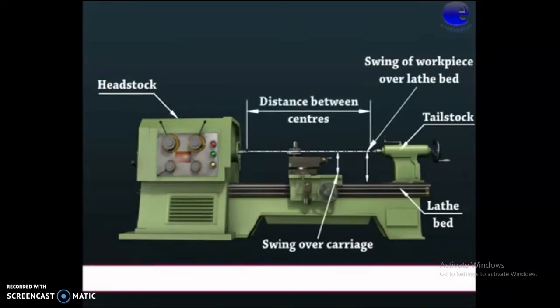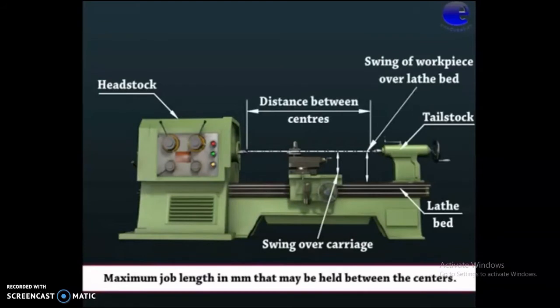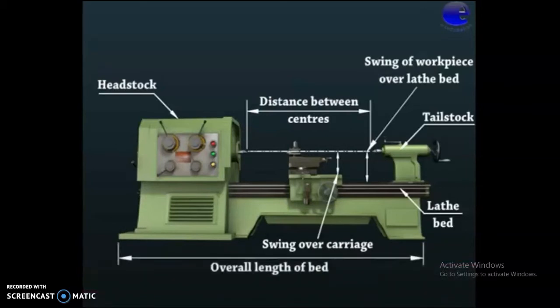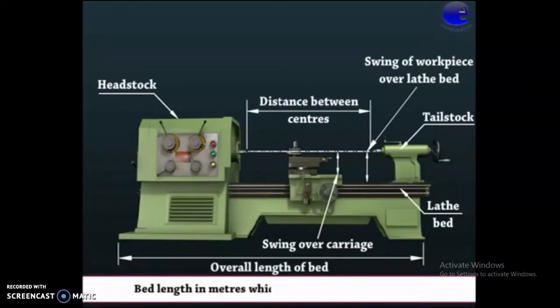Distance between the centers. Maximum job length in millimeters that may be held between the centers. Overall length of the bed. Bed length in meters, which includes the headstock length.